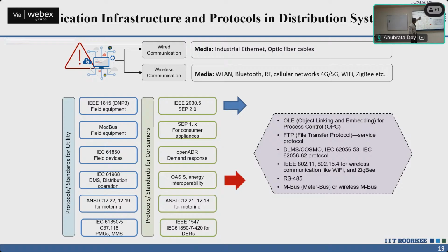So if the utility is using IEEE 1815, then the consumer is going to use IEEE 2030.5. If the utility is using IEC 61968, which is for demand side management, then the consumer is going to use, let's say, OpenADR or some other similar compatible protocol.